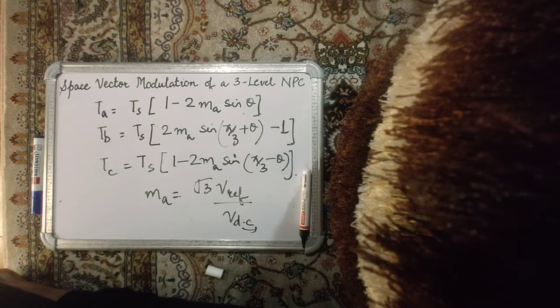Each point is much closer to a circular trajectory than it would have been in a hexagon with only six corners. Now you have points within the hexagon, and even on the hexagon you have more points. So it's always easier to trace that circle or that sine wave with more points, and therefore it is possible even with a lower switching frequency.